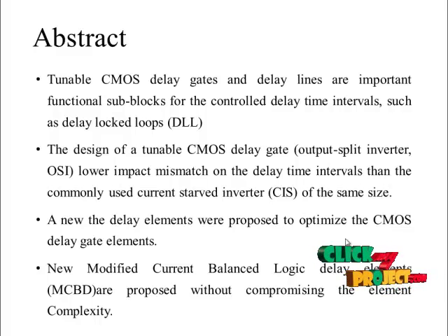Here, the optimization of the circuit performance in terms of parameter variability usually focuses on reducing MOS device mismatch by minimizing the variability of physical parameters of the transistor. A commonly used approach is transistor size scaling, based on the assumption that the local variation averages out when the gate area increases. It has been shown that the parameter variability observed between identically designed MOS transistors relates to their gate size.